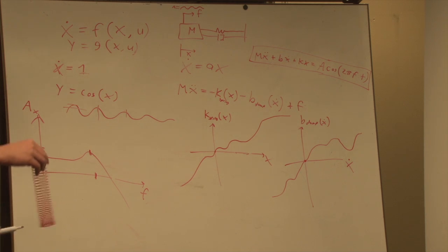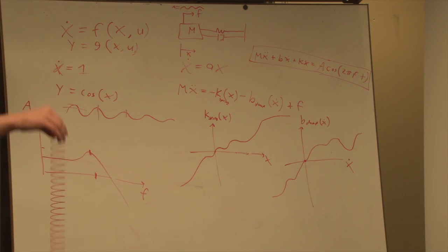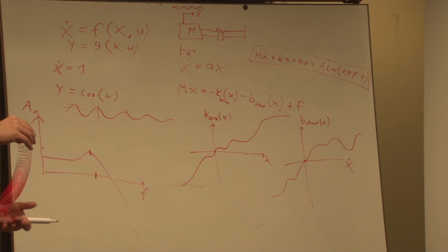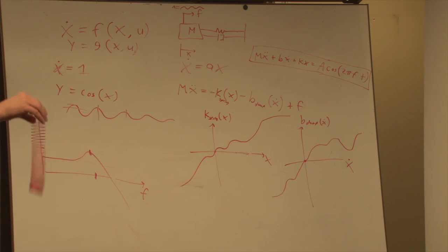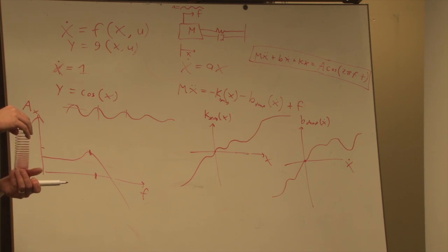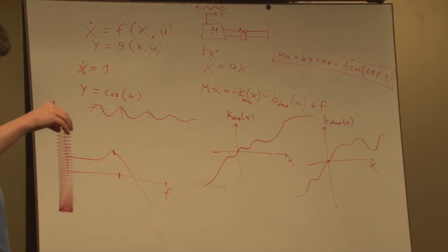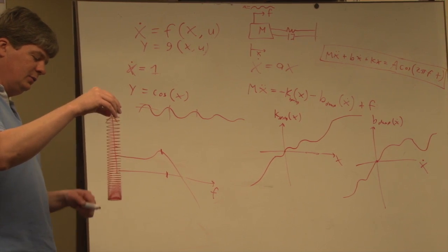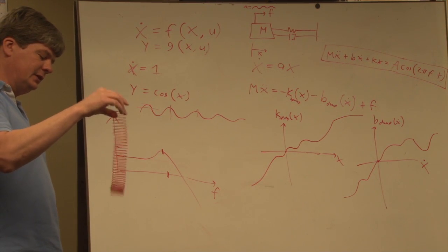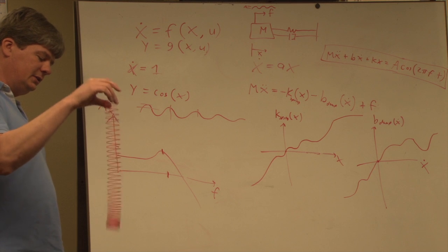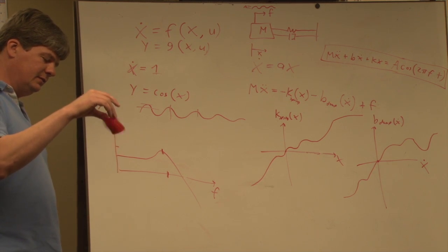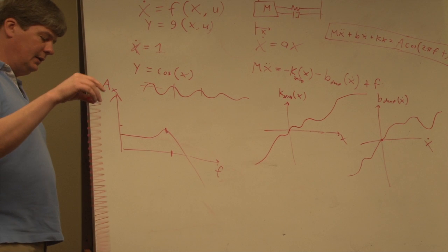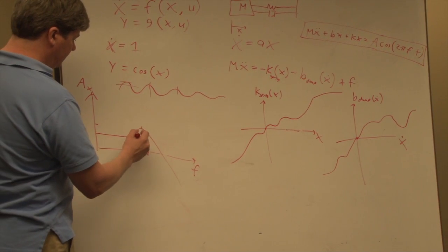Okay. Right, so if you take a spring and find its resonance frequency, for very small amplitude of the input, you get high amplitude of the output. Okay? Well, that's at resonance. Now at low frequencies, it'll just kind of move with you. If I can move slow enough, the amplitude is pretty low. And then at really high frequencies, the amplitude's low. But at just the right frequency, I can move my hand just a very little bit, and I get a large output. So that's at resonance.